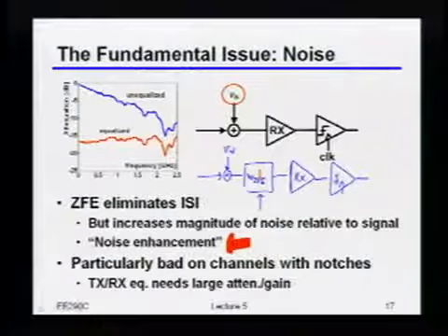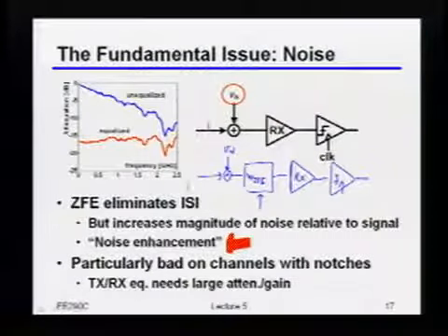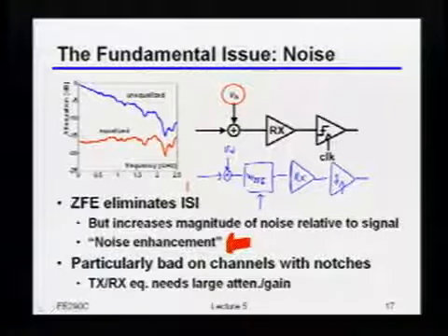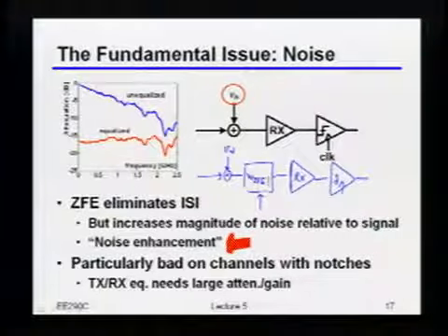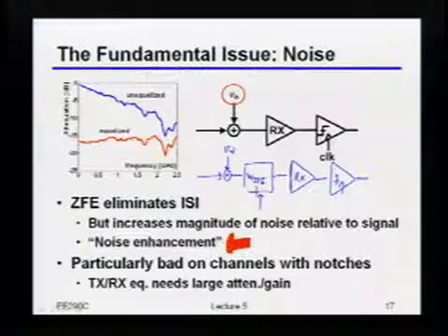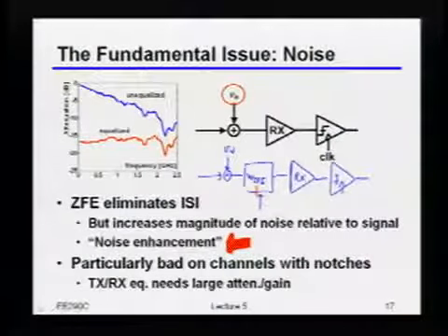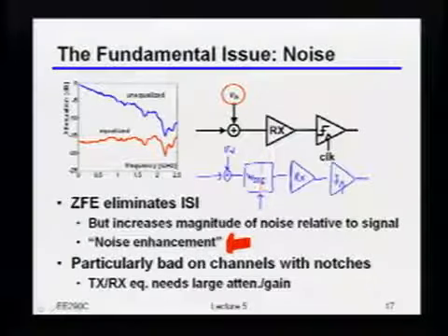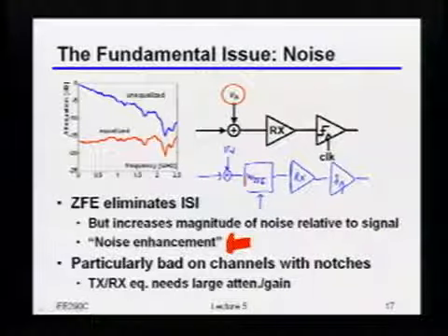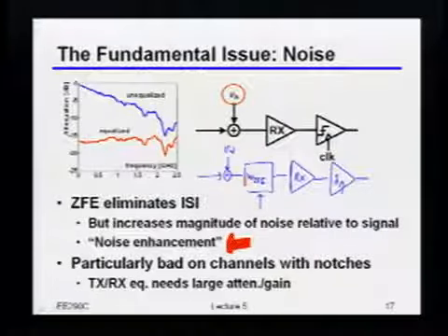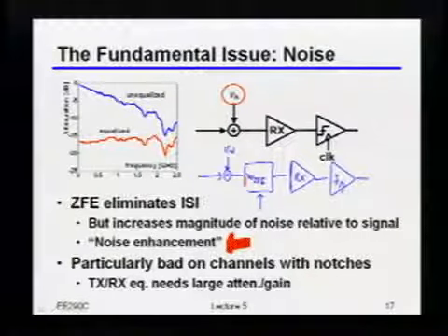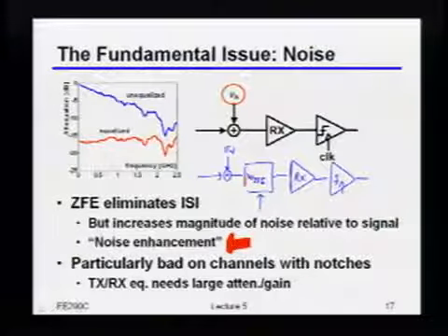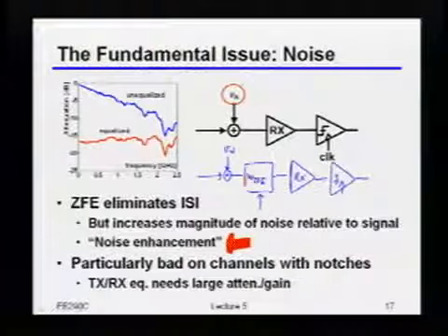When you talk to the comm guys, they're really focusing on sort of that kT noise floor. Okay, that's really what they're mostly focusing on. But this same idea actually also applies even if you build it with a real circuit. And by the way, even if you're not talking about real fundamental noise, sometimes people will tell you that something like this looks bad simply because essentially you'd be amplifying things like crosstalk more, right? Because you're sort of doing a high-pass filter, and the crosstalk might be high frequency, so you might be amplifying that. Other questions?